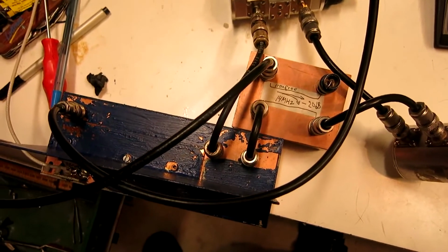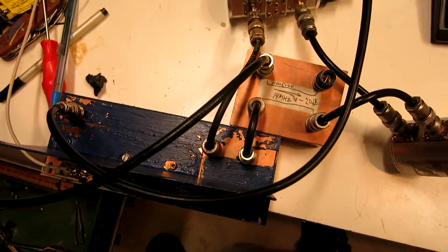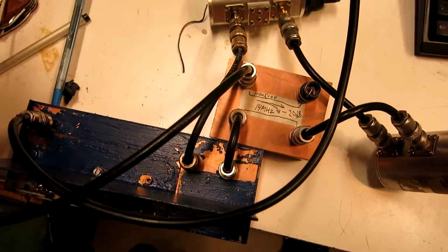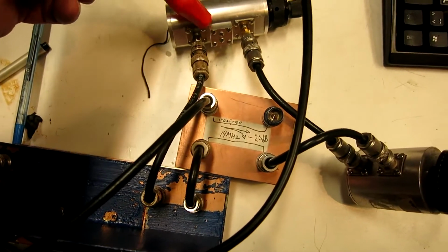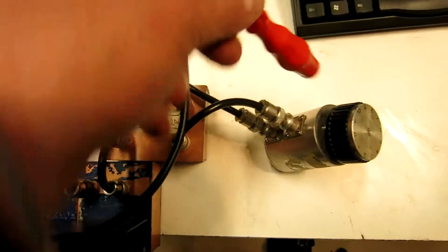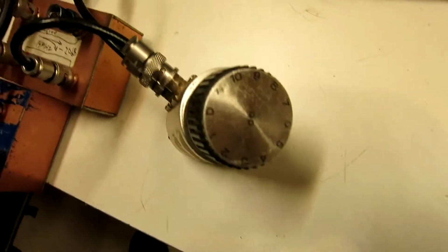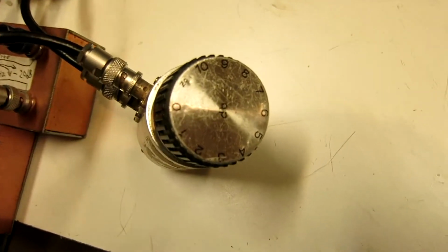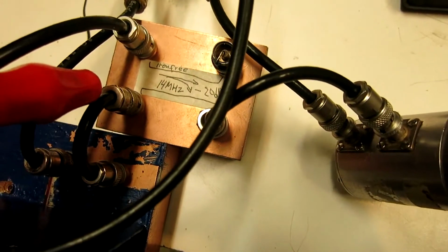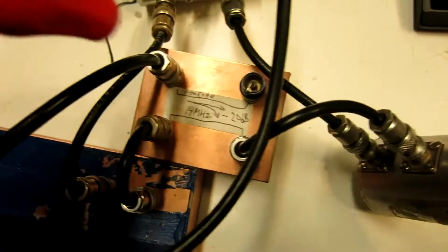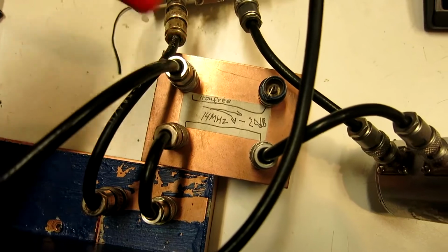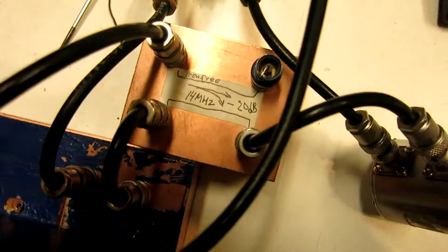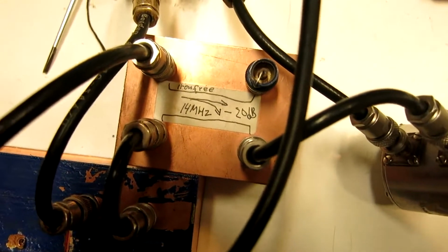I have connected attenuators and a directional coupler. From the feedback output here, there is a first attenuator and then a second attenuator here. And this one is now set to Z0, it means infinite attenuation. And then through a directional coupler, and into the directional coupler I connect the test signal from a network analyzer. And this is what I can see.